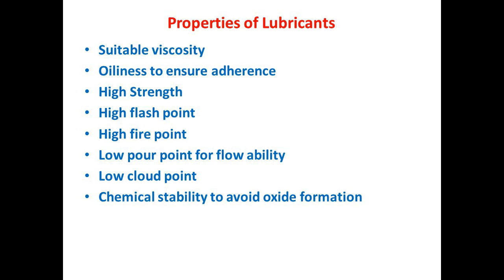The very first property of lubricants is viscosity. Viscosity is the measure of the resistance to flow, or internal friction, of the lubricant. In parallel to the term viscosity, the viscosity index is the governing factor while selecting lubricants. It is used to grade the lubricants.